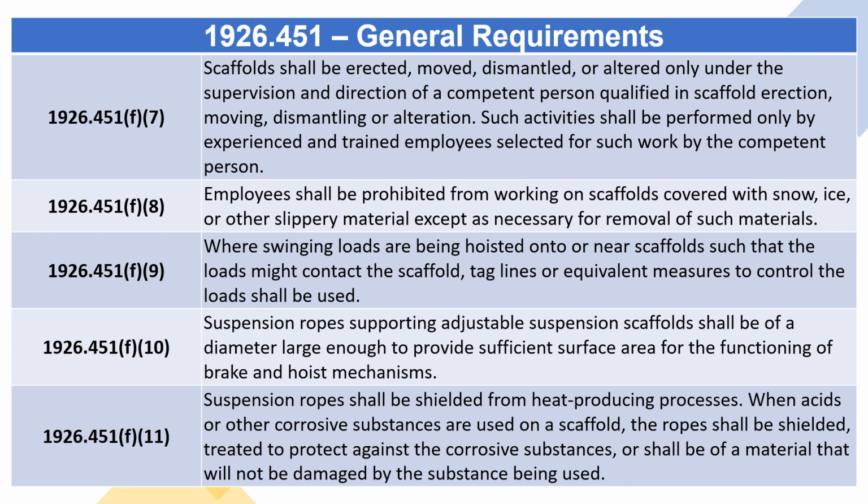1926.451(f)(8): Employees shall be prohibited from working on scaffolds covered with snow, ice, or other slippery material except as necessary for removal of such materials. 1926.451(f)(9): Where swinging loads are being hoisted onto or near scaffolds such that the loads might contact the scaffold, tag lines or equivalent measures to control the loads shall be used.